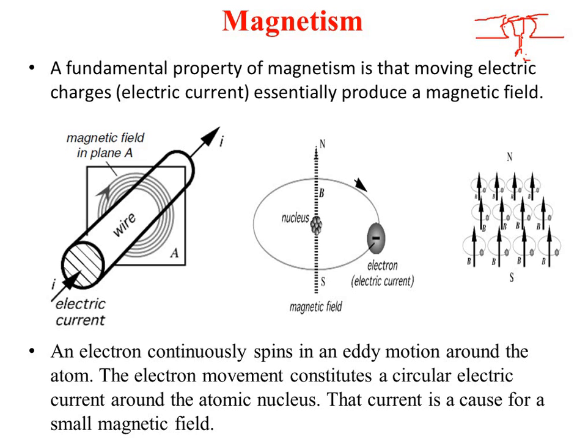Because of passing the current through this coil, it will experience a force in a particular direction depending on the current. How much current you are placing in that coil, the deflection of that coil is proportional to the current. So that concept was used in various meters to measure voltage and current. This magnetism concept was also used to measure voltages and currents in ammeters and voltmeters.